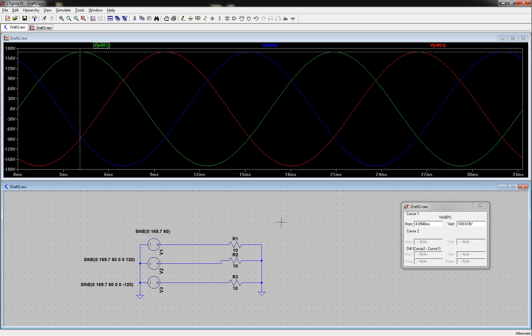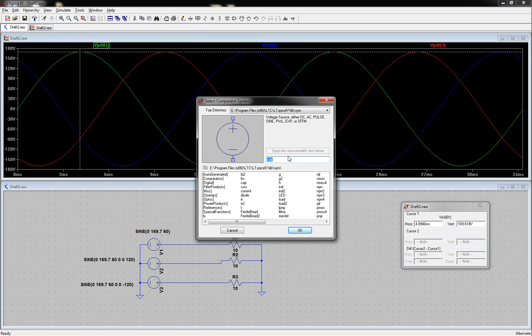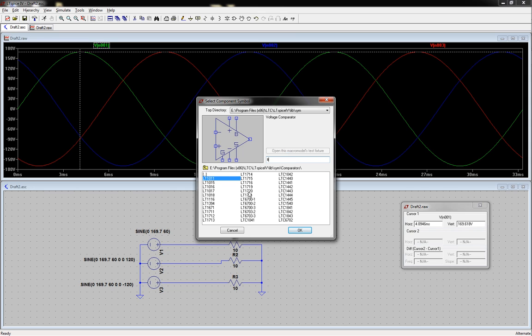What I'm going to do for the next one is we'll probably start dealing with models and how to pull in models, because in LTspice, if you type in LT anything, pretty much everything that Linear Technology makes is in here as a model, like all their different op amps and comparators and reference comparators, even the LTC stuff, all their different drivers and all their cool stuff. Well, what happens if you want, let's say, a Texas Instruments part or a non-semiconductor part? Well, that's not modeled in your little library here.